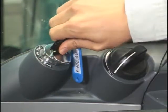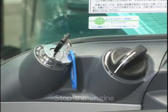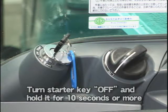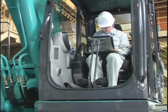Then stop the engine. Turn the starter key off and hold it for 10 seconds or more. It is stored to the ECU while you are holding the starter key. The specification learning of supply pump is complete.